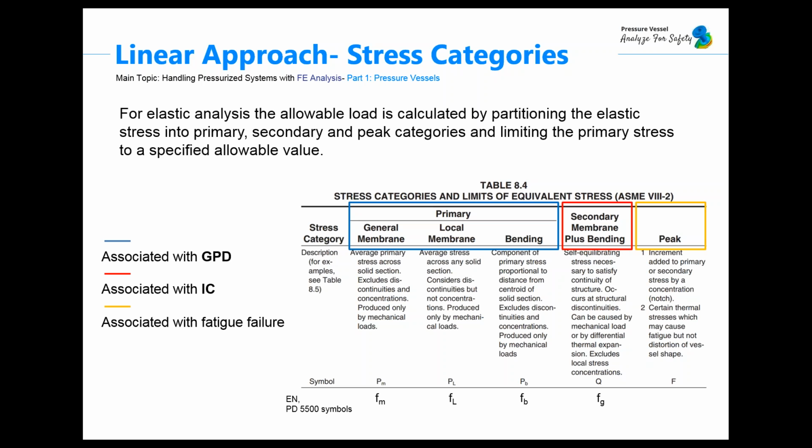So general primary membrane stresses are self-explanatory. They are membrane stresses with the characteristics of primary general stresses. So it's very easy. And these are found remote from large discontinuities, so far from large discontinuities like cone-cylinder intersections and nozzles. And examples of general primary membrane stresses are membrane stresses at the center of a flathead, or circumferential and longitudinal stresses within a pressure vessel.